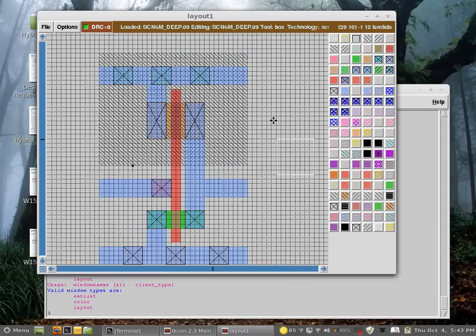Now there are other cells, like a multiplexer for instance, or a flip-flop. They are much bigger than regular cells, and they take 2 times the height. If it's 2 times the height, then they can align with other gates. If you place 2 other gates on top of each other, they would align. But you don't have to worry about that now.